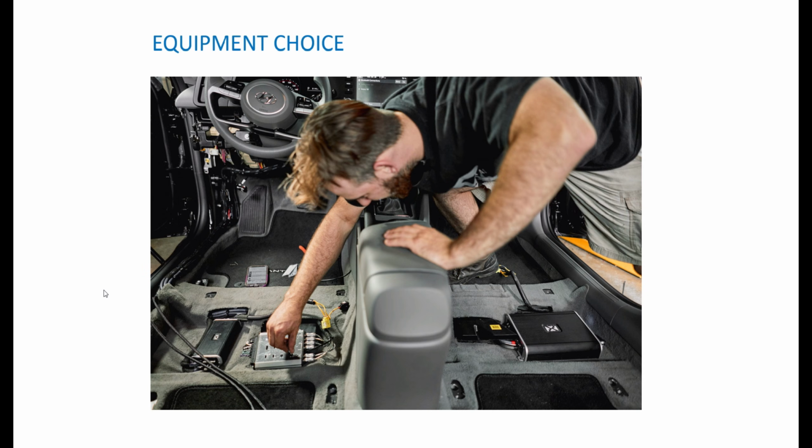Okay, so once you've identified that location, well then you're not going to be able to go out and buy 3 foot long AB class amplifiers, right? They're simply not going to be able to fit, so you're going to be restricted to D class small form factor amplifiers, and maybe instead of having an amplifier for every speaker, you're going to have an 8-channel amplifier, right? Who's going to run a bunch of different speakers.